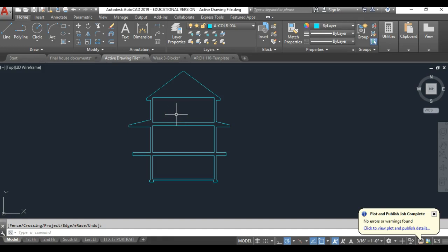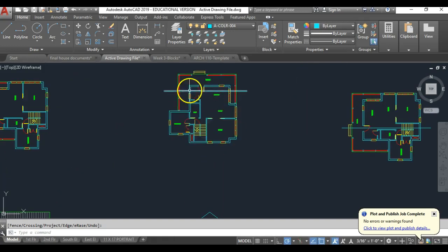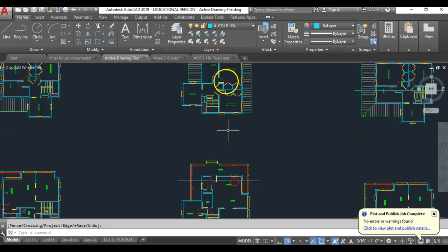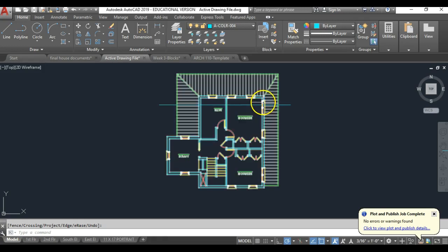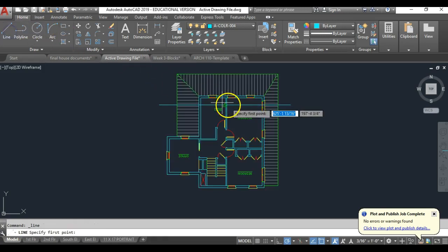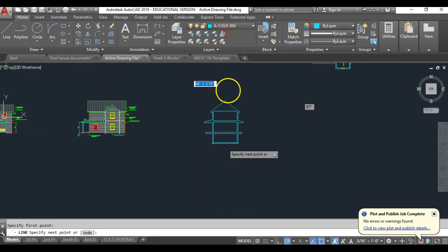Actually, there's only one more wall we have to draw. There's other details which we'll get to in another video, but there's only one more wall, and if we actually look, we have to draw the interior walls and where we cut through. On the first floor, in this plan, we don't cut through anything in this section cut, but if we look up here on the second floor, not only do we cut through this exterior wall and this exterior wall, but we also cut through this interior wall. So I need to take lines down from this interior wall and cut it straight down, right?